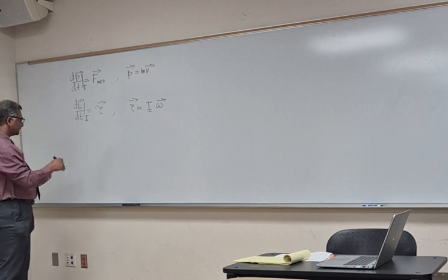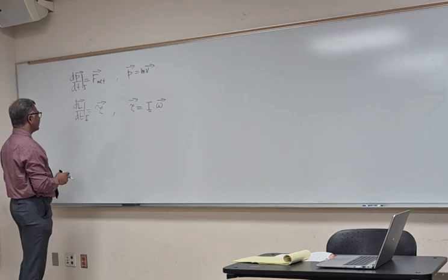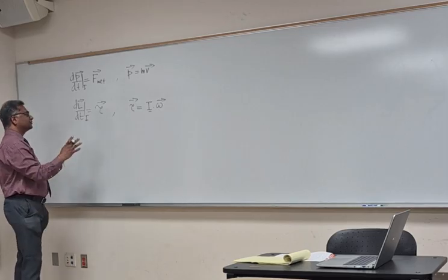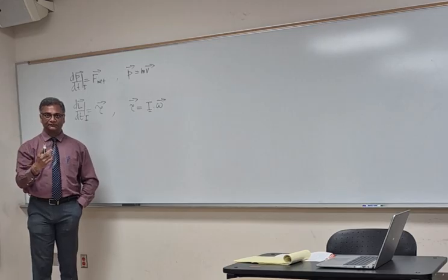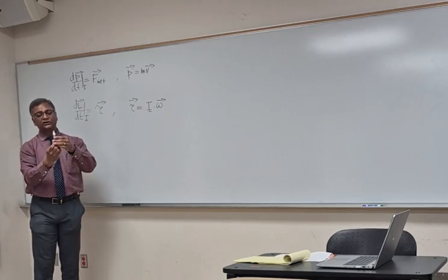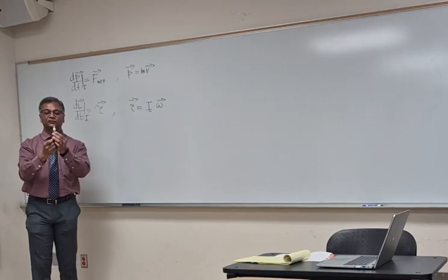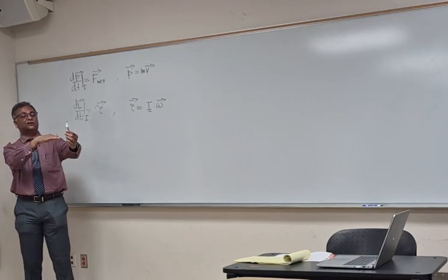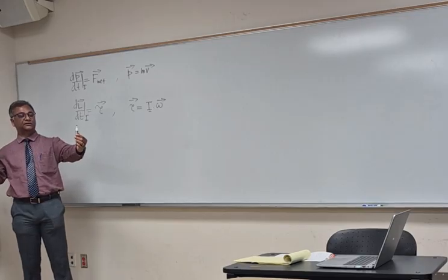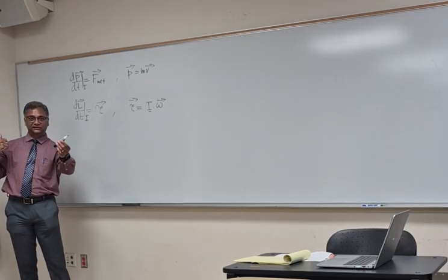But when we are talking about rotating solid bodies, it's preferable to do it in the rotating body frame of reference. Why? Because when an object is rotating, as you saw, it can tumble back and forth. If you look at it from the inertial reference point of view, then all these x, y, z axes are changing.